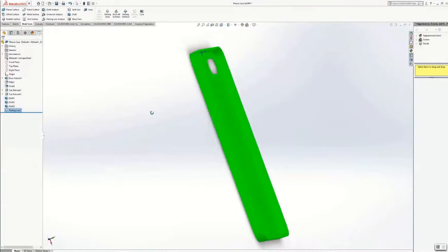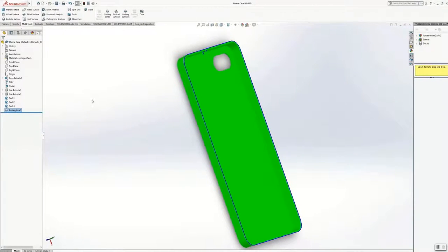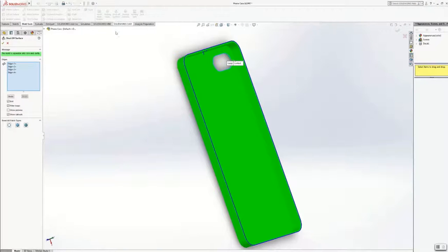The next step is one of the most important steps: shut off surfaces. This is a step that, if it is not completed correctly, you will not be able to continue building your mold. You will know when you have to shut off all surfaces because the holes will not be filled. There can be redundant loops, but you will just need to delete one of the loops depending on which side you want the cavity to be extruded. We will show this later on.